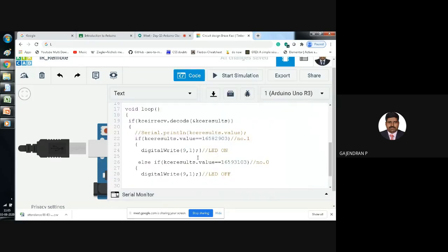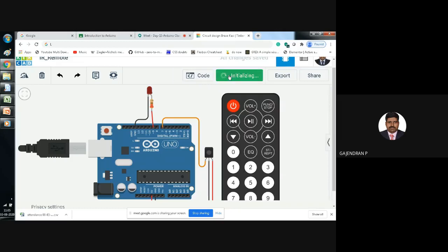I think we may not have changed the logical value. See, here we forgot to change the logical value. See our program flow and the logical value you are checking; in the same fashion you can debug the program. The on condition is okay, meaning nothing is wrong in the on condition statement. Only the off statement I need to check. In the off statement I made one mistake: I forgot to change the logical value. Okay, now I start simulating this one.